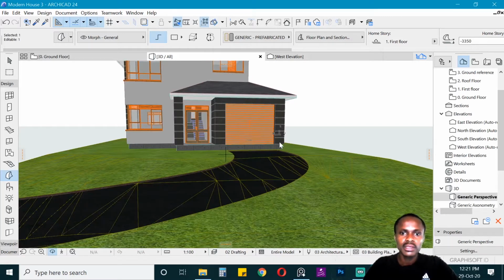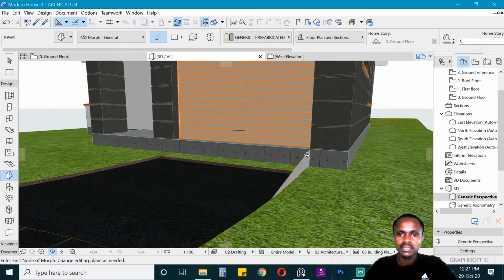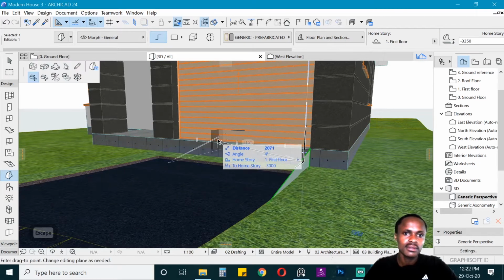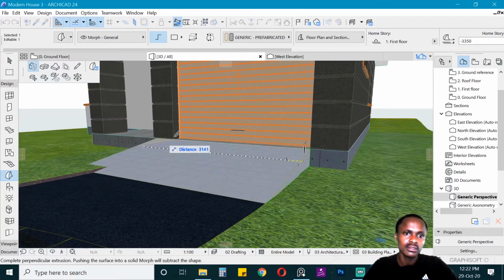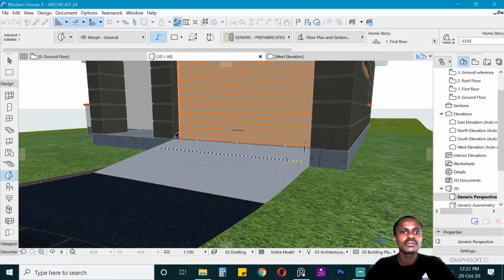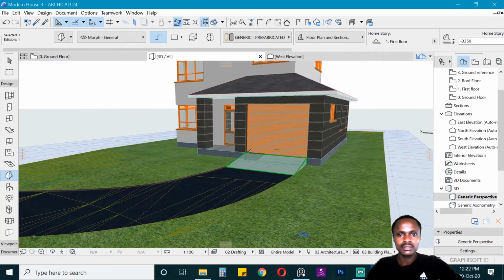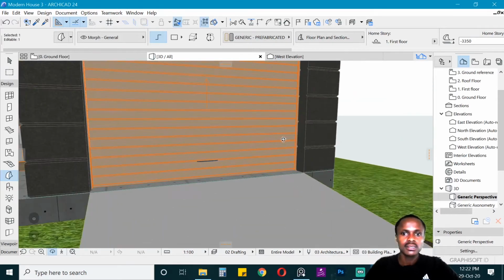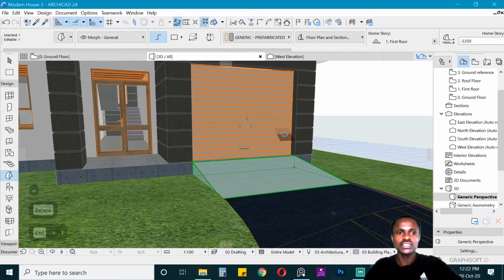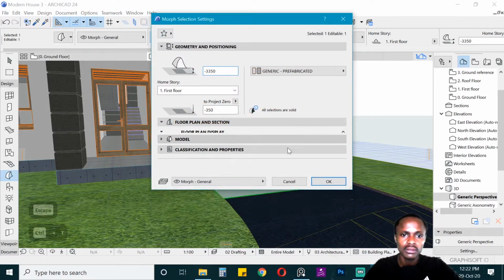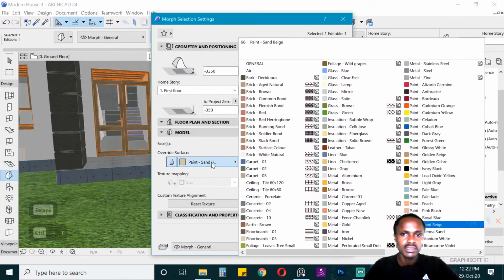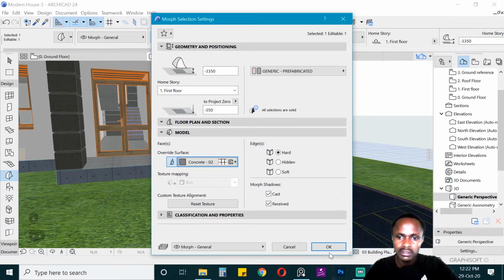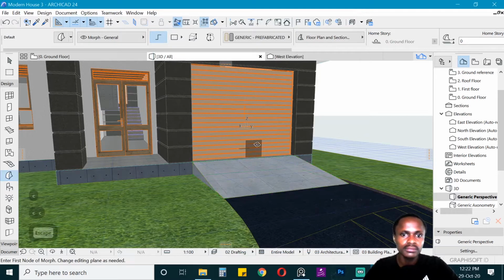So we go in 3D, just come here and give this depth. And, yep, 3 meters away, and that's it. So we have dealt with that axis. Of course, we can change how it looks. So we can decide that maybe this one should be a concrete floor. Concrete, maybe this time 0 to.